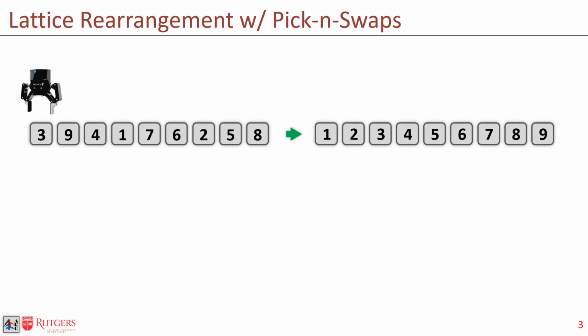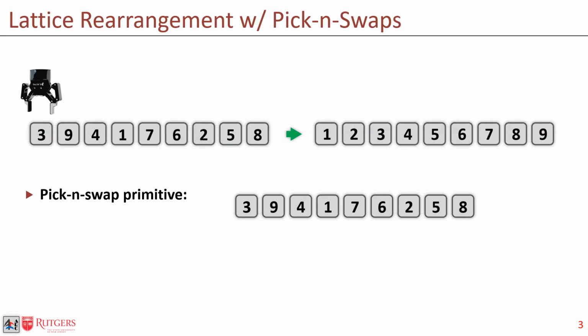In rearranging the items, we assume a pick and swap model, where the robot may pick up or drop off items, move around, and make item swaps. For such a problem, a plan P may be fully specified as a sequence of end-effector locations P0 through Pn+1, where P0 and Pn+1 correspond to the end-effector rest position, usually at the top left of